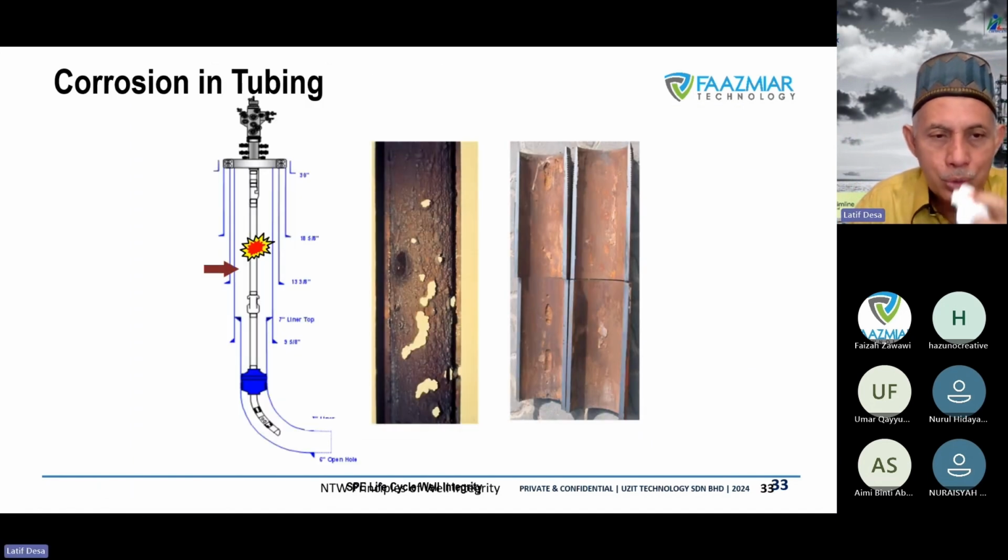Okay, now we go to corrosion in tubing. You can see how the tubing can be badly corroded once we have water coming in, then you have the failure in the tubing. And once you have the failure in the tubing here, you cannot flow normally. The production starts to flow, we come into the annulus and try to push the rest of the liquid downwards if there's any leak here. But so far, you are not able to produce because most of the well flow will be mixed up with the packer fluid below here, and then it starts to mix up with the water coming up. So we have a problem with the packer fluid here. It's supposed to be there to protect against corrosion of both tubing and casing, but once you have a leak, then you have to shut down, and of course you have to pull out the tubing, under the term called recomplete the well. So pulling out and rerunning again with new tubing to continue your production.